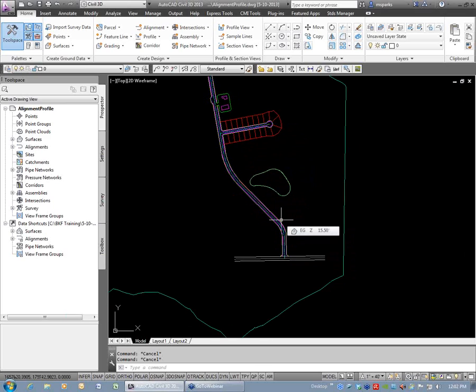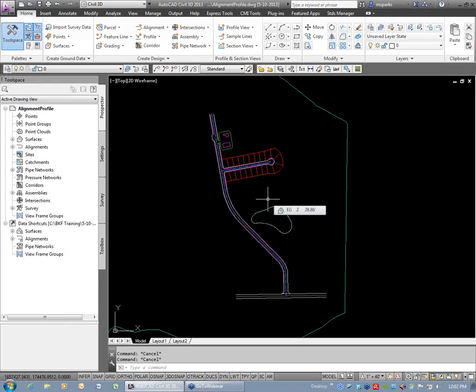Okay, so we're basically going to be looking at the drawing from a standpoint of this is a template that is just out of the box. So I know you guys do have templates, etc. So bear with me on some of the styles; they might be a little bit lacking. But first things first, the alignment is the 2D layout, and we're basically going to convert those polylines that are from the X reference to an alignment. Okay, there's other ways of creating alignments as well.